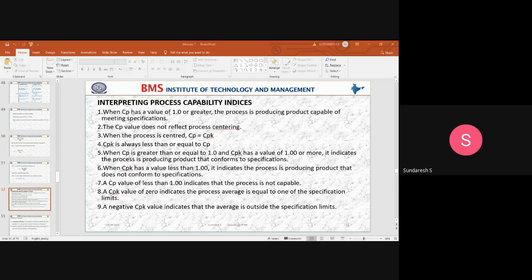So this amount of variation should be permitted in the dimensions because of the effects from the man, machine, and the material. That permissible variation in the dimensions, we call it a tolerance. So we call it a dimensional tolerance. In the sense, we are permitting the dimension to vary from its nominal or base value, above or below. The above value we call the upper limit, and the lower value we call the lower limit. So the variation between the upper and the lower limit constitutes the tolerance for us.